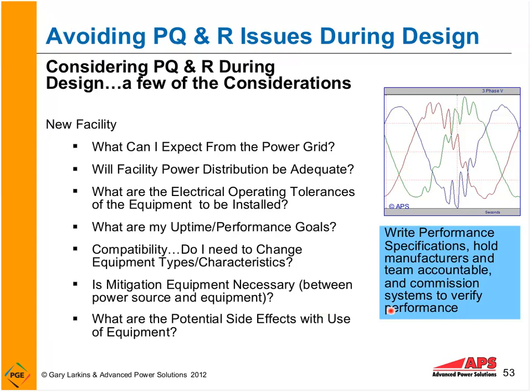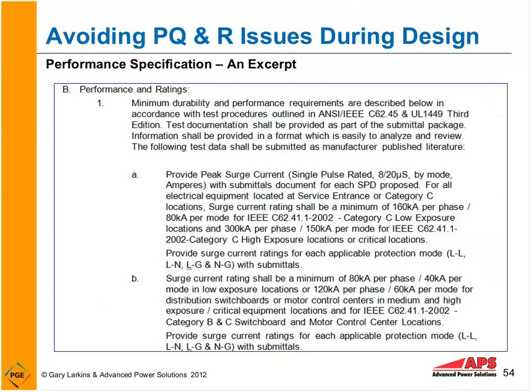So I always suggest writing performance specifications. How do you want the system to perform? Hold manufacturers and the whole team accountable, and then commission the system to make sure it's operating properly. Here's just an example of a performance spec.